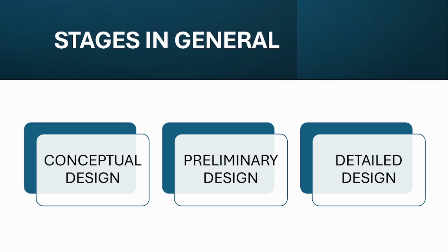Then it goes to the preliminary design stage, where you design not only the outer view of the aircraft but also the internal structure, and go through all the engineering protocols which are necessary for creating some systems, structural design, analysis, etc. And finally it goes to detailed design, where you go to the level of each rivet to create final engineering drawings. After those stages, the prototyping, testing, certification and manufacturing phases come, but maybe that's the topic for another video, not for today.